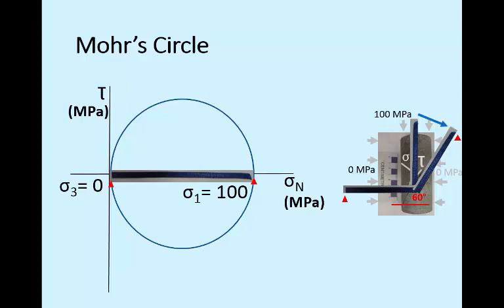They are both plotted on the x-axis because the corresponding shear stresses are 0 for principal stresses. Once a circle is drawn with the diameter represented between the maximum and minimum principal stresses, all the points on this circle represent a stress at a different orientation for this given mass, this given unit length, and this given stress combination. In a few slides from now, I'm going to show how to calculate from first principles the stresses at different orientations, just so that we can prove that the Mohr's circle really works.